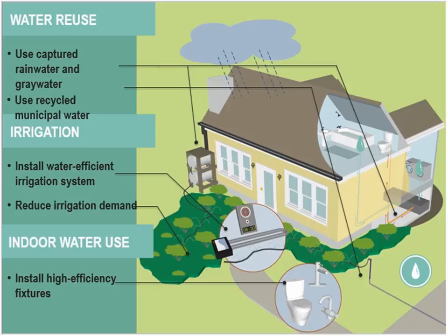Then there's the shower head and the faucet in the bathroom, not in the kitchen. We don't care about the kitchen in this current version of LEED, just the bathroom. Getting those down to 2 gallons per minute or lower, you start picking up some extra points in the rating system. And after that, you can go outside and start looking at the water irrigation.